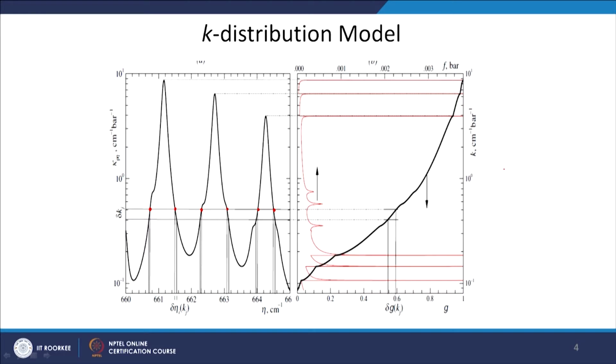Only for these points, intensity is not a function of wavelength, rather it is just a function of k, where kappa lambda is the spectral coefficient. Ideally for each wavelength or wave number the intensity should vary, but because the absorption coefficient is the same, we write that intensity is just a function of k, where k is the magnitude of absorption coefficient at these wavelengths that I have highlighted.